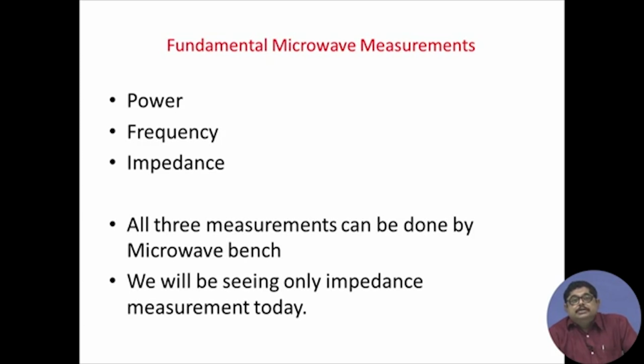Also, you should know how to measure frequency, and as I said, impedance is a very important thing, because in both low frequency and high frequency, impedance characterizes the network. A network does not get characterized by its voltage excitation or its current response, but by the ratio. Whatever your response or excitation may be, the characteristic of the network is inbuilt in its impedance. That is why impedance plays such a major role in electronics, and we have again said that amongst electronics engineers, RF engineers are very careful about impedance, for impedance matching and having the optimum power delivery.